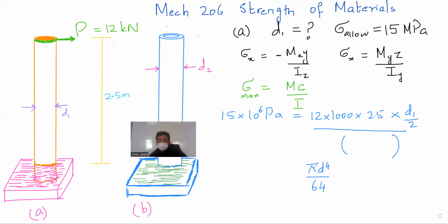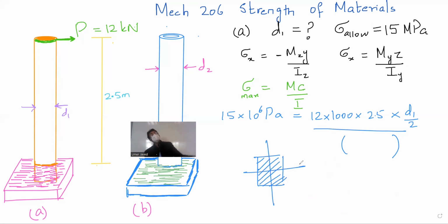So if it were symmetrical, it would not be the half, right? Very good. His question is, if you want to find polar moment of inertia, then moment of inertia about this axis plus this axis will give you the polar. I'm pretty sure, but yes, I will add them together. But for this structure, about this axis and this axis, it's not the same. But for a circle, are you following me? You bend it like this, or you bend it like this. Either way, it's a circle that is bending, right?